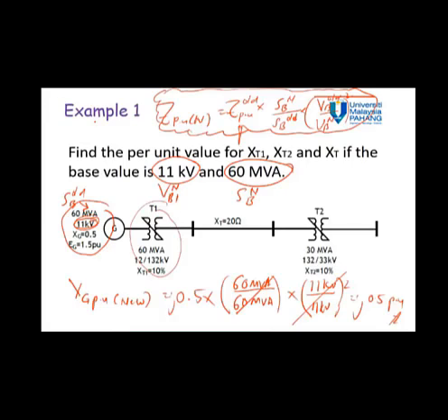Usually before we start our analysis, we have to convert this single line diagram into the impedance diagram. So the first step, we draw the impedance diagram.